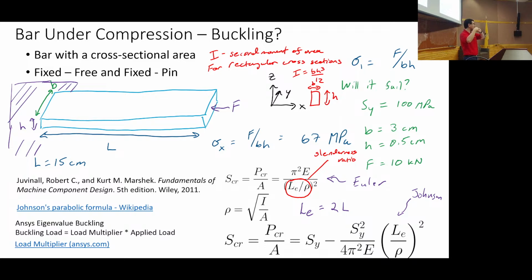It can buckle in the other direction, that is a mode of buckling, and you'll see it more in the vibration analysis for the homework. But that's much less likely than buckling in the direction of thickness. The H is what determines that. If you want to know how it buckles in the orthogonal direction, you have to calculate those stresses and flip the B and H.